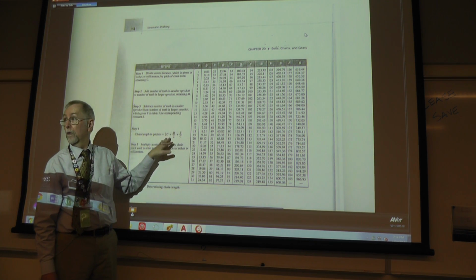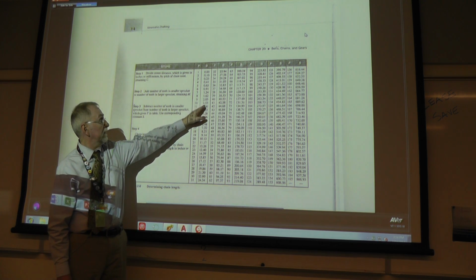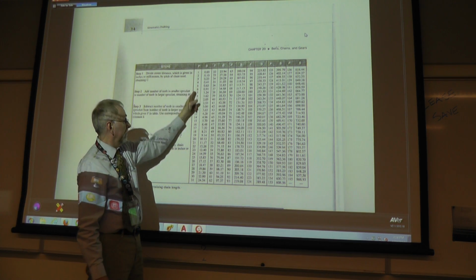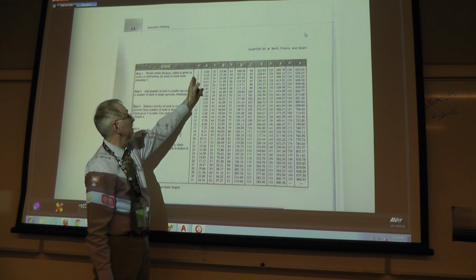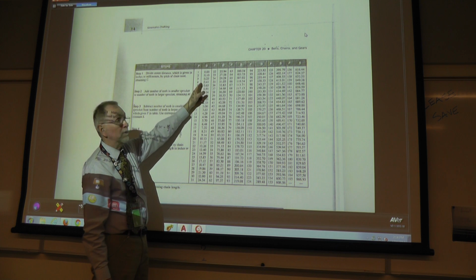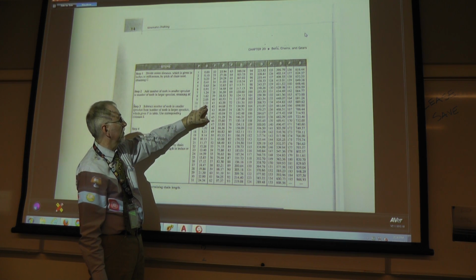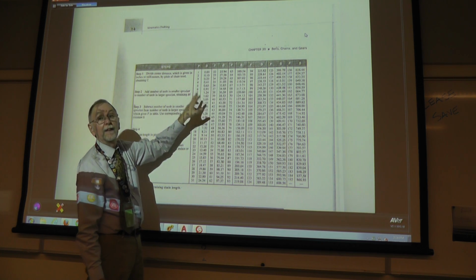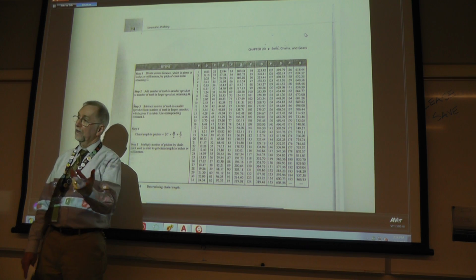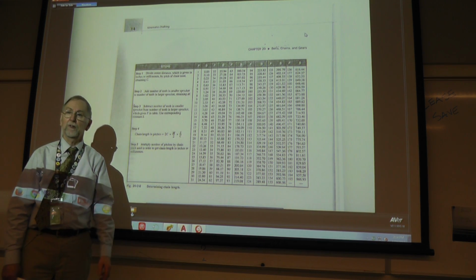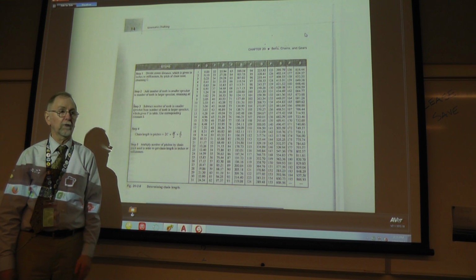F's not in this formula. F is something that we find by calculation. The number 10 then gives us, so I have a column for numbers that would fall in that calculation, which equates to a number that comes in the next column over. So 10 would give me an S number of 2.53. That's how S is determined to put back into the formula to figure out what the length of the chain is. Confusing? A little bit. But you know what? That's how chains are calculated.